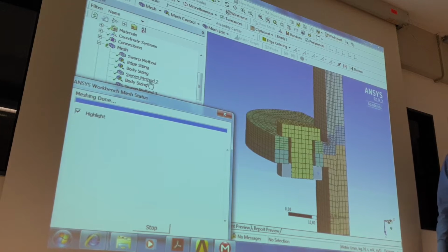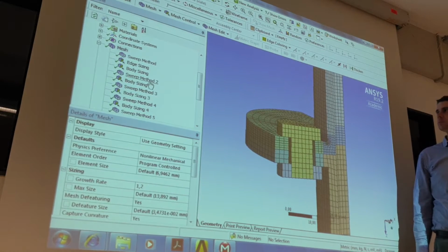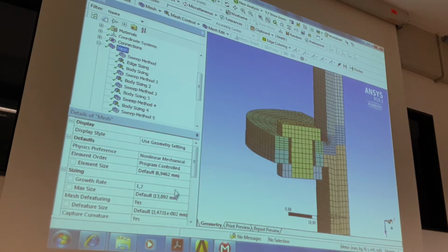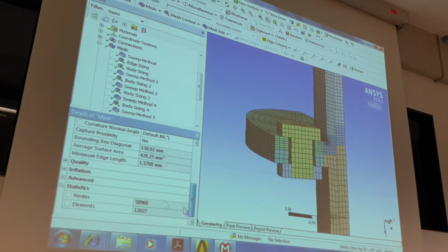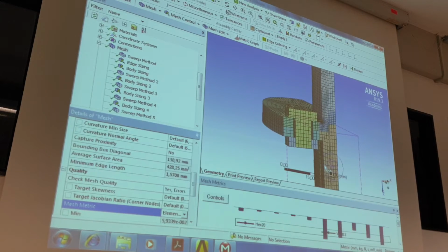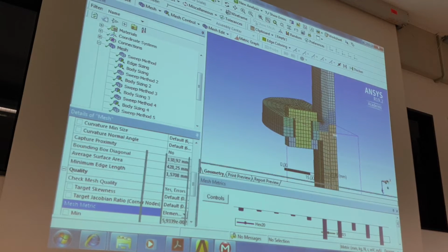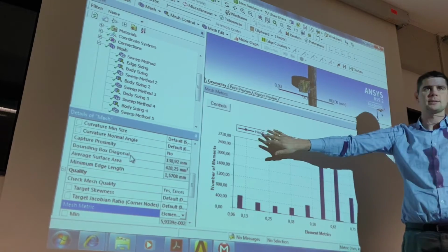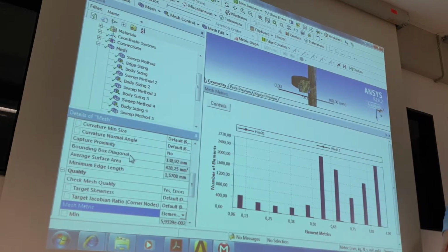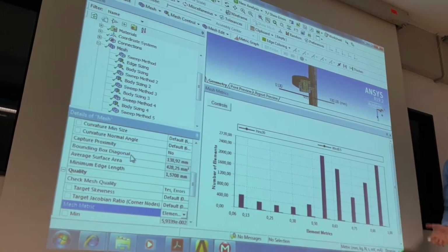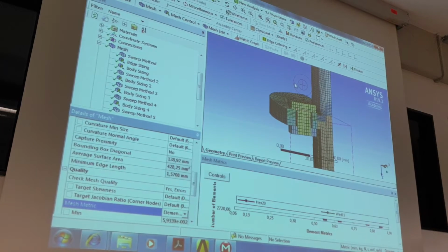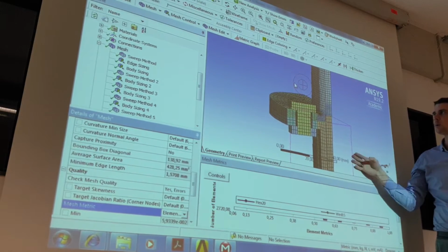So it was all about meshing. Okay, and now we can calculate this meshing. We can also show statistics of meshing, I think quality. We can say mesh metric, element quality, and then in the element quality we will see which kind of meshing we have. You see we have always hex 20 nodes, and sometimes pyramidal, which we needed to connect it. So it's a perfect mesh, no tetrahedrons, super good. It's only with some small things. So okay, we created good meshing.